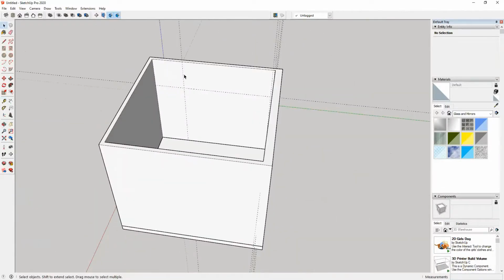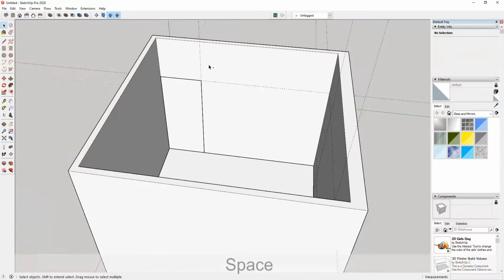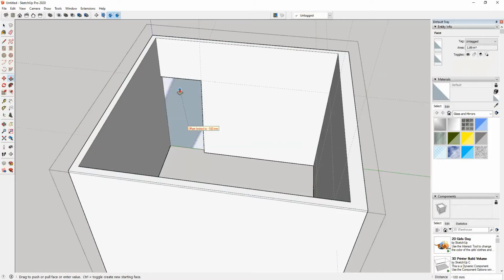Now in order to create the openings, if I go on creating a rectangle here, I will not be able to push pull it inside the wall, right? So to create a push pull or modify the walls, I need to go inside the group, and I will be able to create the rectangle. And this time I had divided the face in two halves, as we had seen earlier, and I'll push pull it. Now it will say that push pull is limited to 100, because at 100 it will erase the original face, and it will create a puncture.